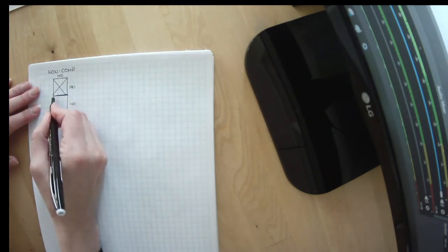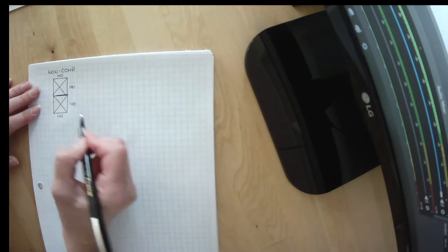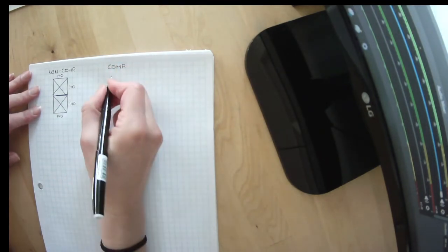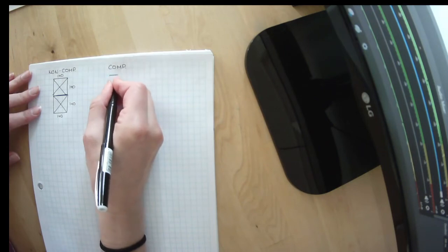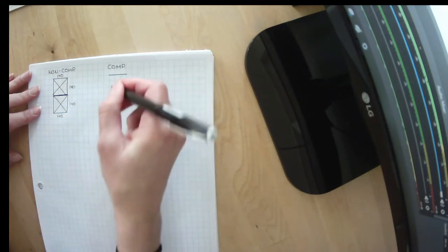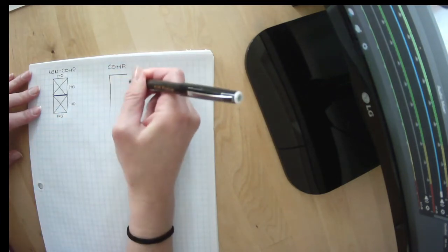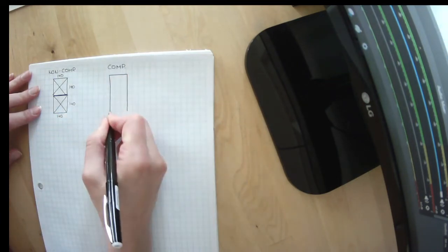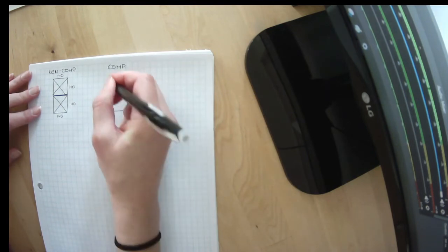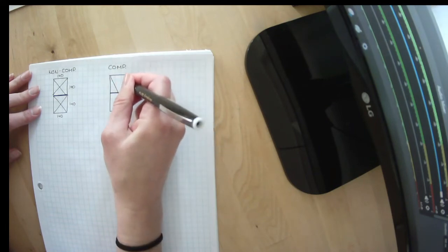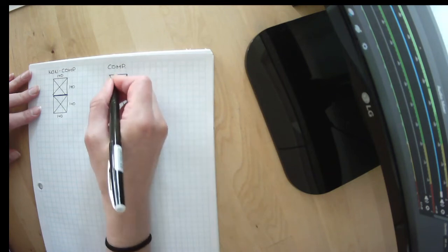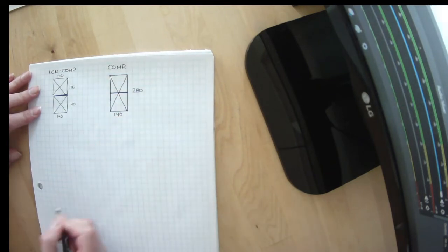These are two separate objects that have not been bonded together. Composite means we have glued them together or attached them along this plane in a way that they work as one member. So we've glued in here in some way that we have one member that is 280 millimeters deep by 140.